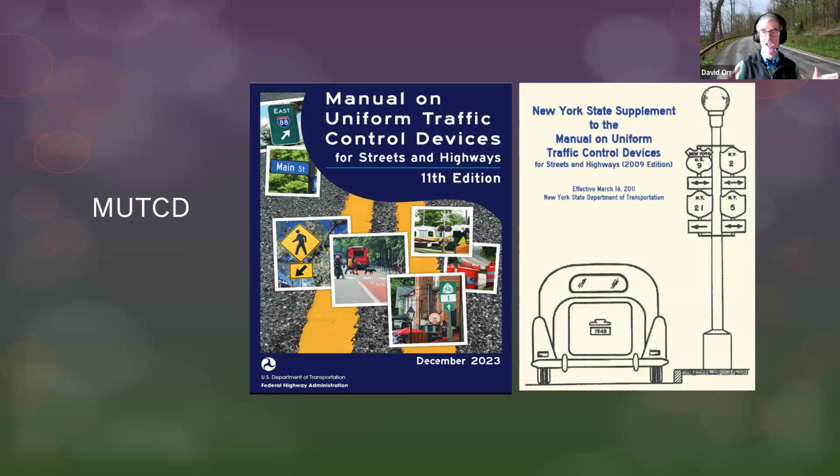Because you all know that on a nice, warm summer day with good tires and a good car, you can go around that corner faster than the sign says, the yellow sign. But the goal is, if we do our job right, we're providing consistent information. So if we see a sign that says 20 for a sharp corner and the speed limit is 55, that should have the same feel, whether it's a county road or a state road, whether you're in Missouri or New York.